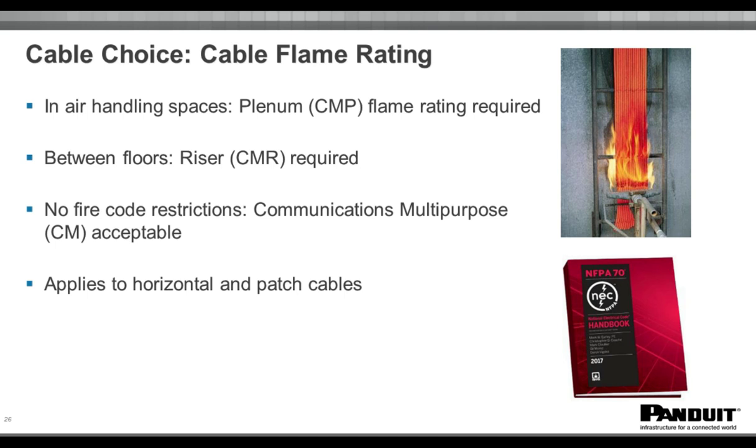This one might be something you guys already know, but I figured I'd review this with you as well: the cable flame rating. So in air handling spaces, a plenum cable or CMP, the flame rating is required. This is the most stringent type of flame rating. Between floors, so perhaps in an elevator shaft, you'll be able to use a riser cable. Also where we're located and where you're putting cable into conduit, a riser cable would also be acceptable.